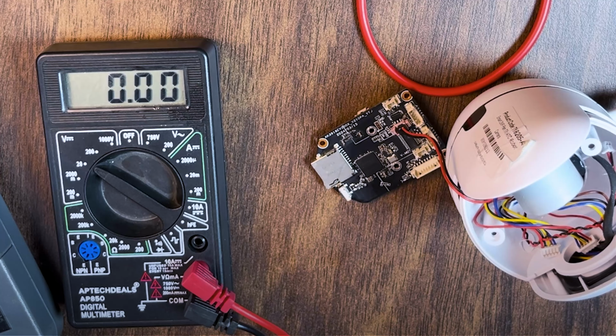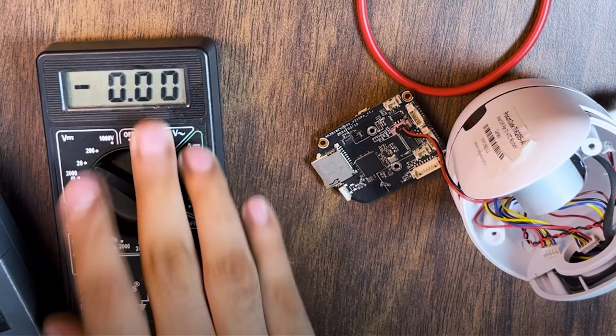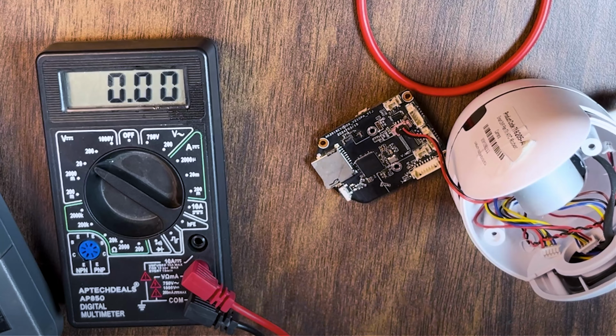Alright, what you right now saw is that our 3.3 voltage was the average voltage that was high over here. And that indicates that this is a stable high voltage. We can say that this might be the RX port. However, the little fluctuations we did see right now could also point towards it being a TX port. So now let's move on and also see what readings we're getting with the TX port to better solidify which of the ports is actually RX and TX.